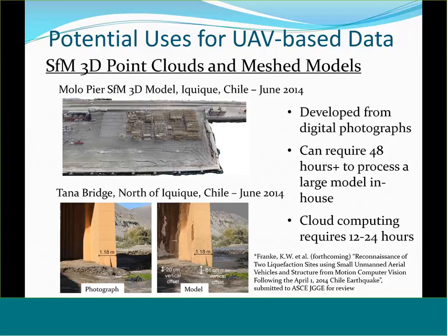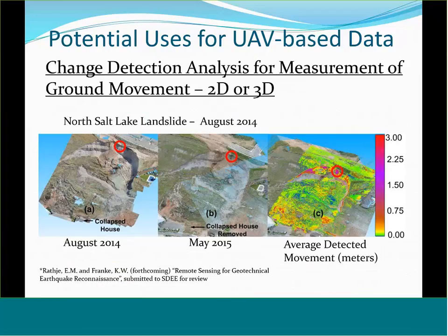A couple of notes about structure from motion. If you're processing these in-house, they can require quite a bit of time, up to 48 hours or more to process. But new structure from motion software programs now are doing a lot of the processing in the cloud, and that's cutting the times down to 12 to 24 hours, and I'm hearing reports of even less in some instances.